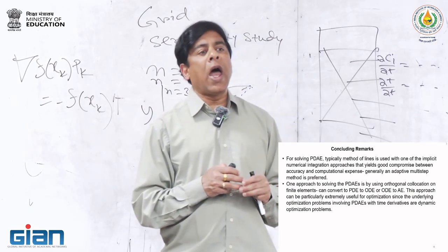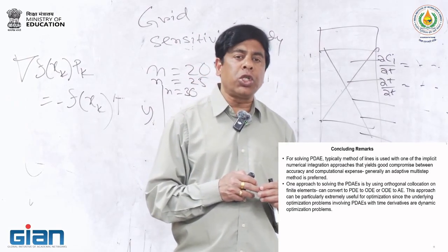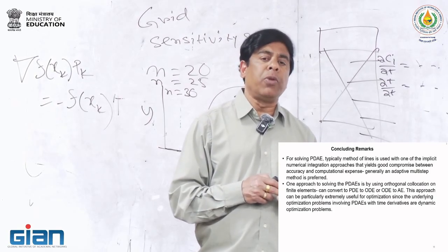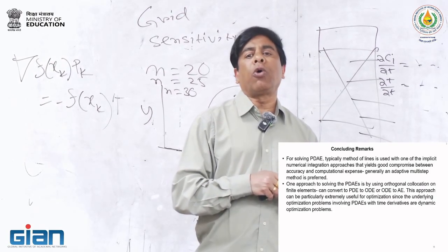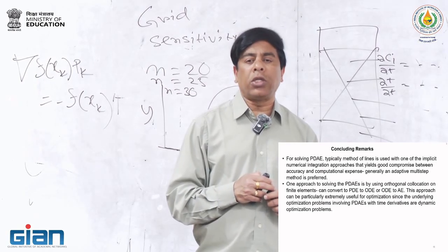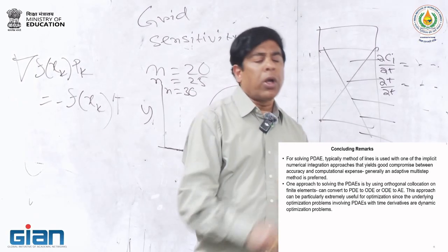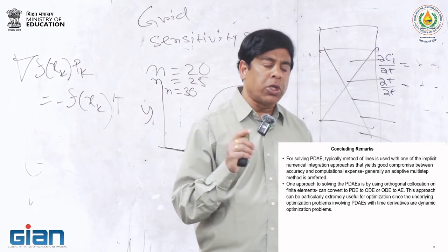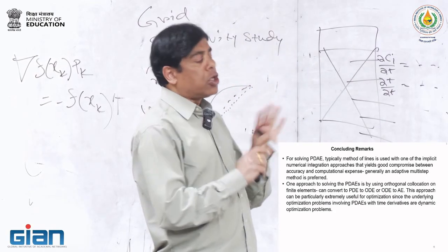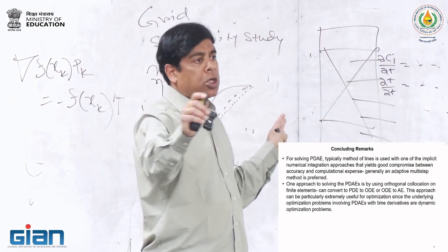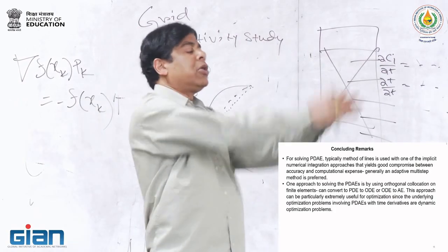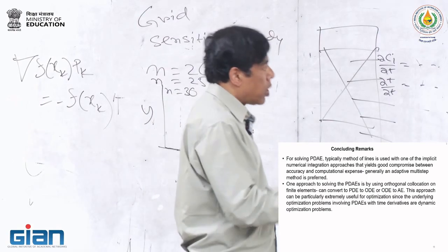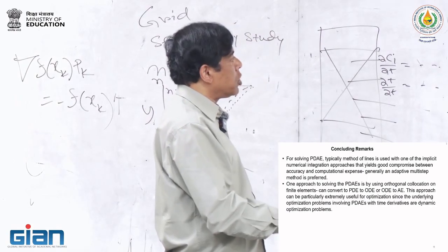Aspen does not have an OCFE implementation, but if you use Python, Pyomo has OCFE implementations with many of the collocation based methods that you could use. For adsorption, we generally use the Radau based collocation methods. It generally works fine. This will be for dynamic optimization. It converts the whole thing into an algebraic model, and then it will optimize the whole thing. Okay, but I will not spend much time on this one.